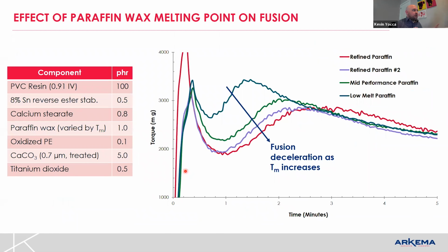When I think about how we modify those two things, things that can be done that are kind of interesting, we can look at different paraffin waxes. So I'm sure there's folks here from lubricant supply in some way or another. No, not all paraffin waxes are made the same, okay? So we have some that are refined, very high melt, and some that are low melt. And you might say, why would I want a low melt? That's cheap, it's not going to work. Well, a low melt wax, if used properly, can be fusion promoting and still give you lubrication.